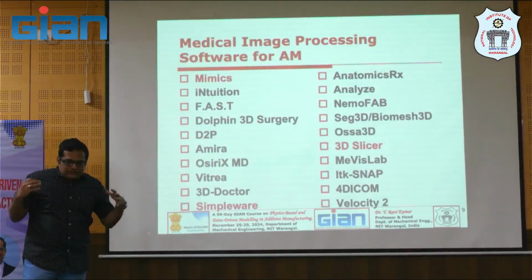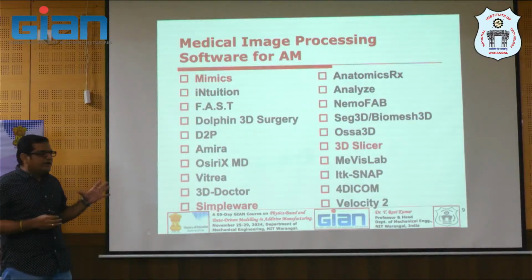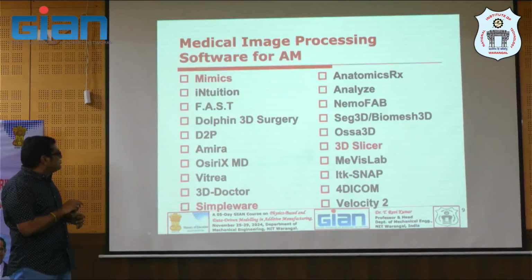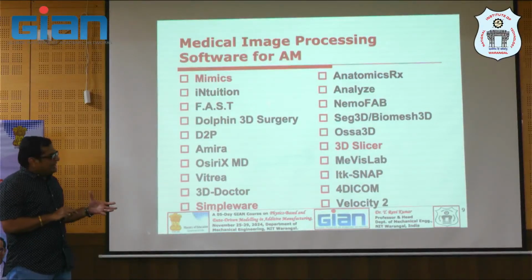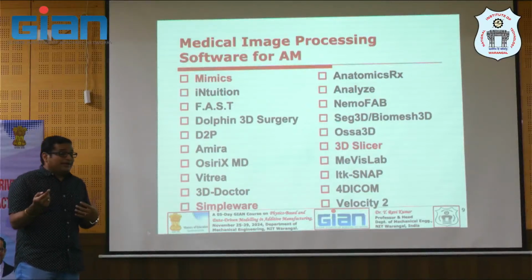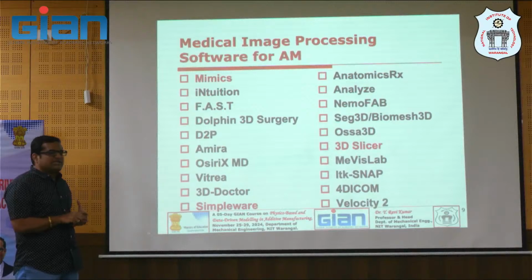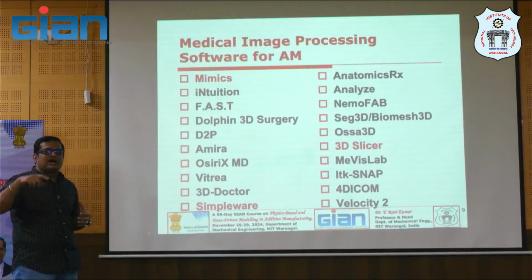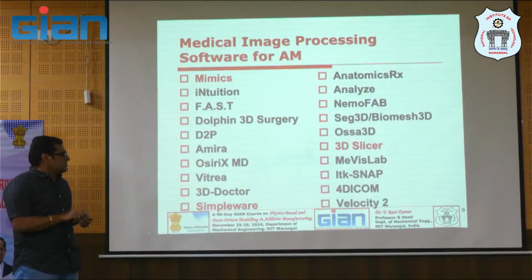So you try to see some tools available in medical image processing software, like Mimics is one of the medical image processing software, and Simpleware is another one. But both of them are proprietary softwares. But if you are looking for an open source software, this is 3D Slicer. It's free of cost. So it will almost have the features which a proprietary or commercial software will have. Basic tools like importing the DICOM images and applying thresholding and region grow and saving as an STL file. So all that stuff can be done with open source software like 3D Slicer.